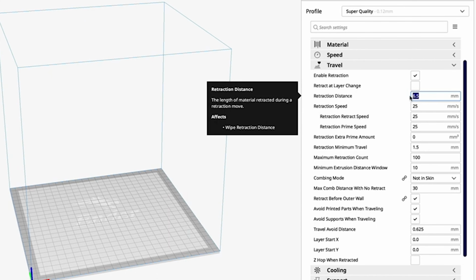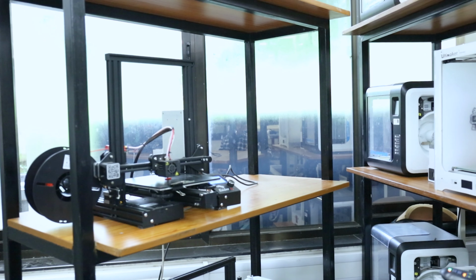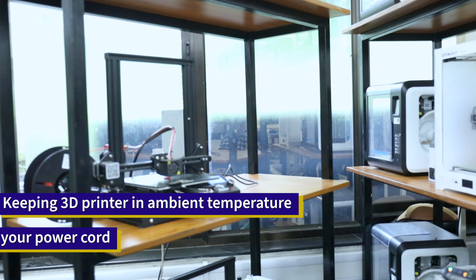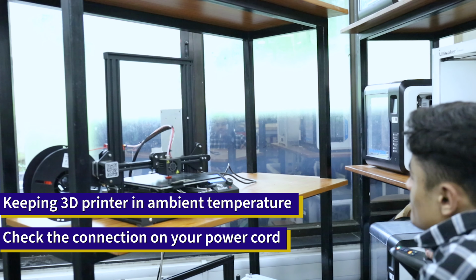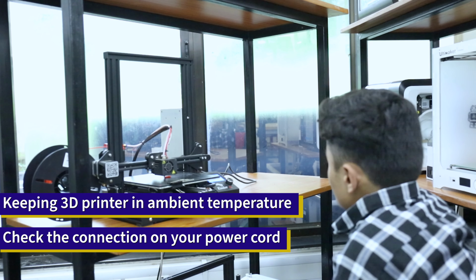Sometimes, you don't want strands of filament cluttering up your precious prints. You can probably combat this by tweaking what's known as the retraction distance. The thermal runaway is another problem you may come across. The solution to this is to first check the ambient temperature, keeping your 3D printer away from the cooling sources such as the air conditioners.